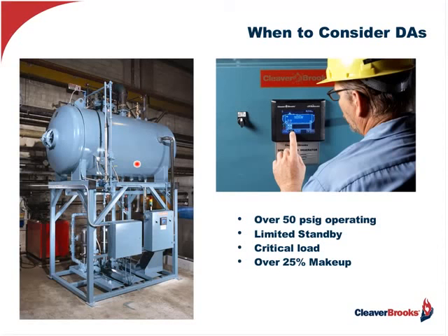And of course, the deaerators and high-pressure condensate return systems today are all controlled with PLC-based controls. So you've got all the control within a single platform, controlling your pumps, controlling the levels, variable frequency drives, logging all the data, communicating the data. This is all available to you in systems today. And it's not just Cleaver Brooks, it's our competition too.